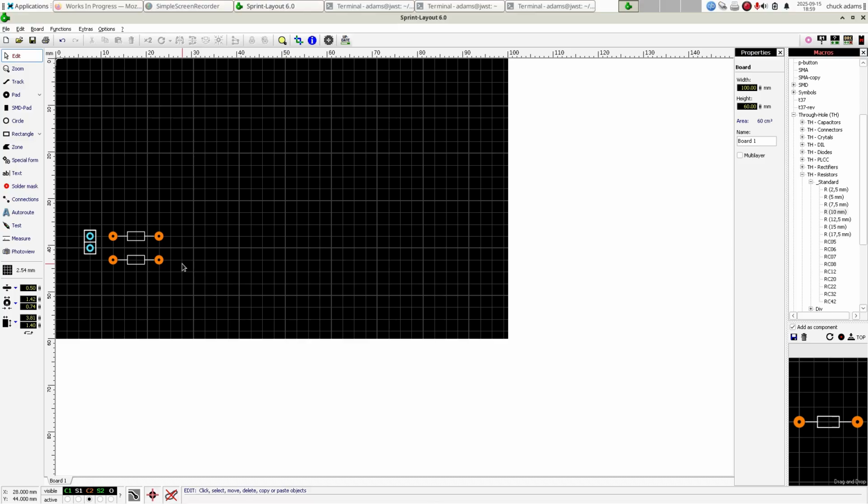On the spacing, you're going to have to learn this. What I would recommend is get one of the little, I call them vector boards. They're little boards that have 2.54 millimeter spacing on holes, and it looks like a grid. And take some components and look at how they would fit between the holes.